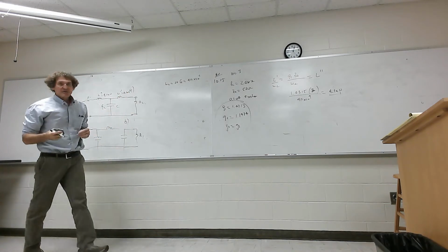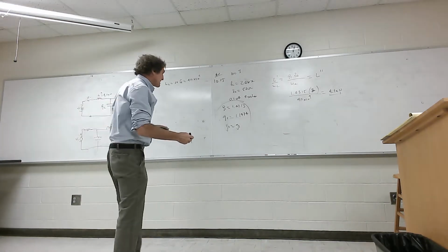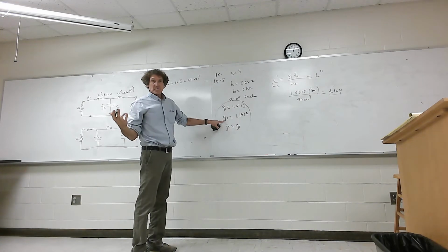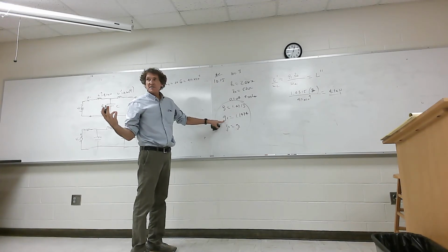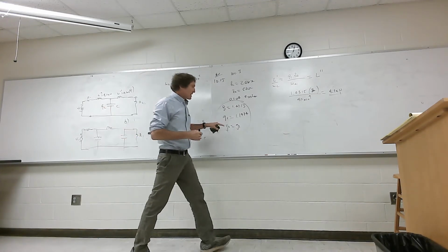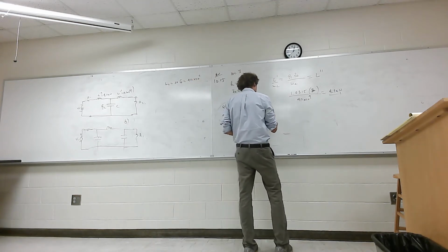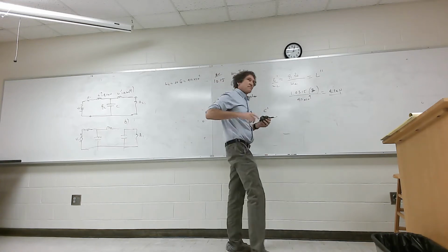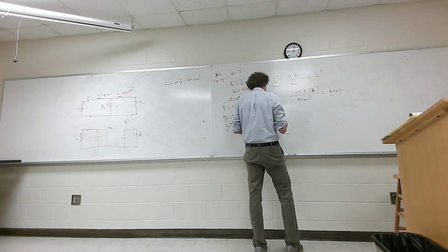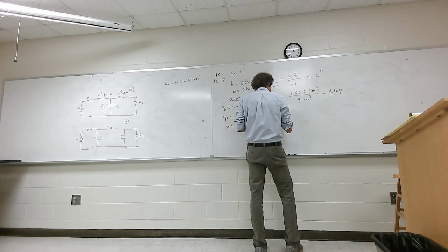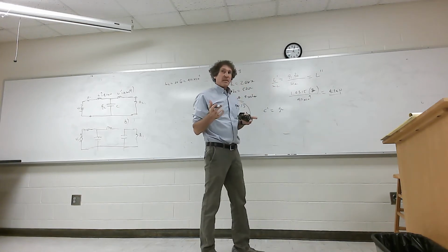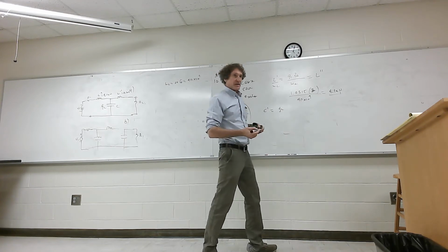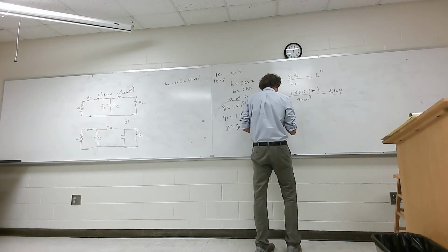Now we're going to get the value of C. To get the value of C, it's associated with G2. G2 is here. Are you with me, everyone? It's not hard to see this, but you got to at least see it. So if I have that, to get the value of C prime, and he does this in an intermediate step way. It's not always done this way, but it's okay. So first he takes the value of that G2, and then if it's a capacitor, you divide it by Z0, not multiply it by Z0. So you're going to divide this by Z0.